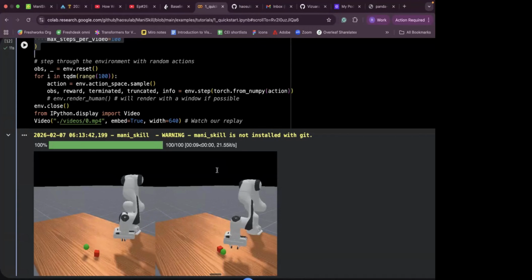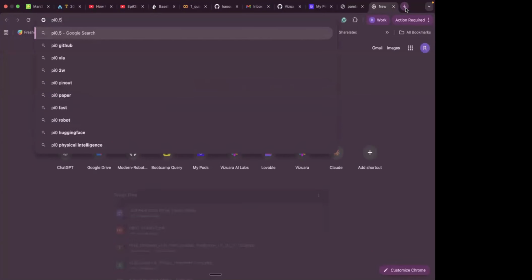Vishnu, if we use this RL to train, does it work with your SLAM in a new environment? Does it figure it out? Actually, people do domain randomization. If you have a simulation environment, they try it with different parameters. Let's say we have a mobile robot and we want to drive it on a surface, they try with different friction surfaces. So yeah, it mostly works. It is robust to some extent, but it doesn't always work. Let's say it works 95% of the time. The long tail is what we always work on.